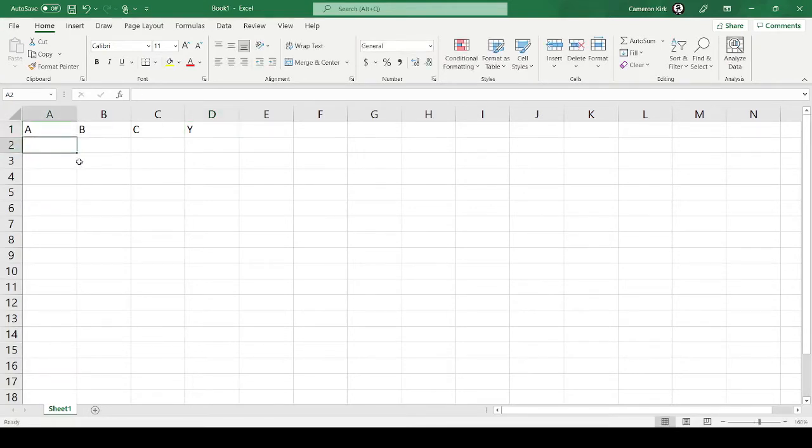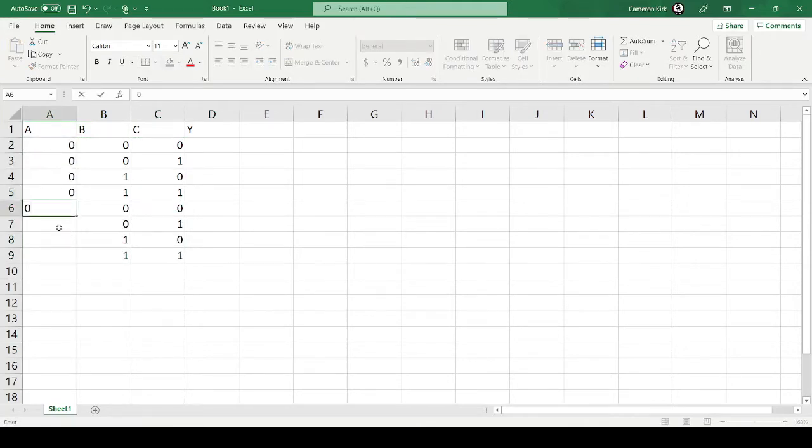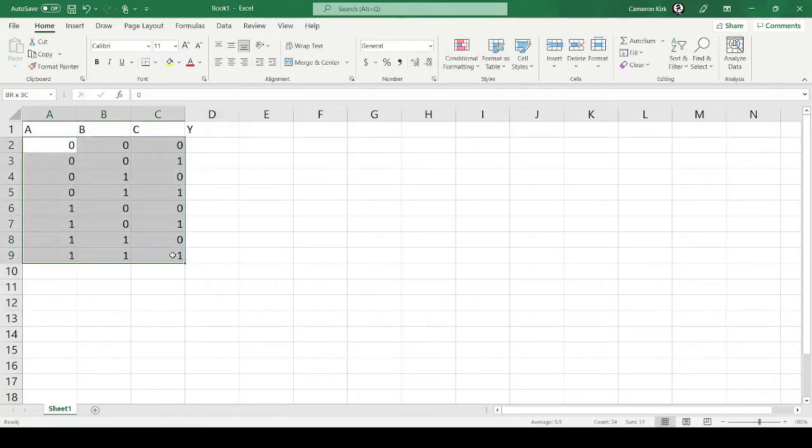So the fastest way that I think to draw a truth table is to come over here and put a 0, 1, and then we'll copy and paste that. And then we'll do a 0, a 0, a 1, a 1. Great. And then we'll copy that whole block, put it underneath. And then we'll do a 0, 0, 0, 0. Too many zeros. We need a 1 here. 1, 1. And that is every single possible combination. I'm just skimming through, making sure I did that right. Yeah, I did. Okay, cool.